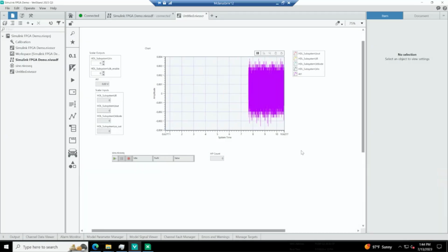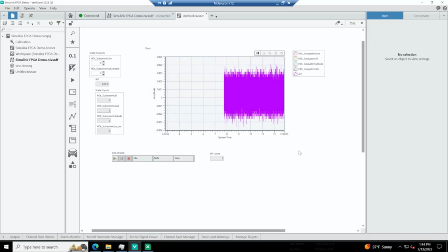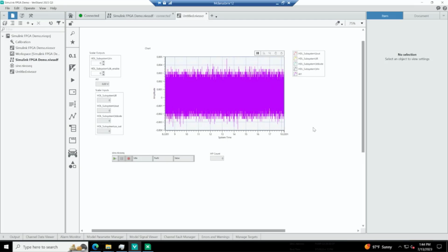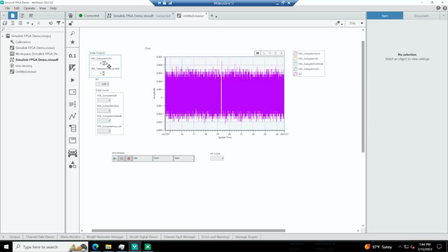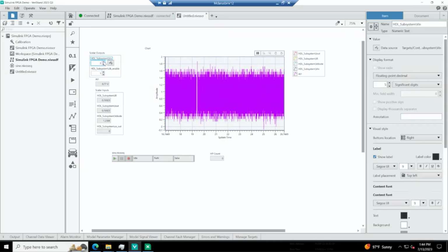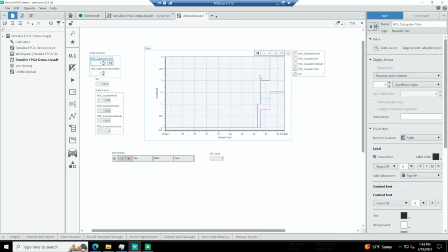And now we are actually seeing responses. So right now it's kind of just the analog input seeing a very little bit of signal. I mean, that's within the range of noise for this device. So I mentioned I can click on my clock enable. Right now I'm not supplying any voltage into my model. In manual, I can just apply maybe a static value, and we'll start seeing some response.